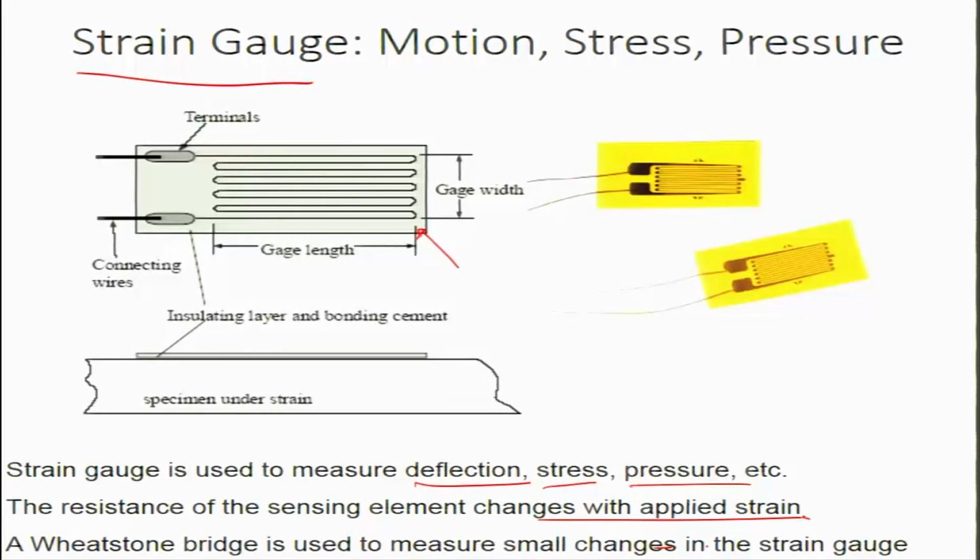As this element is bent or deformed, it changes the overall resistance, and we can calibrate the extent of motion or deformation, in terms of the applied strain, to the change in resistance, to get the strain induced in a real life system by looking at that calibration data for different runs.